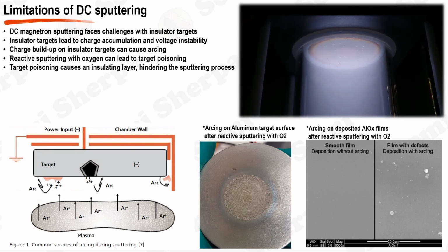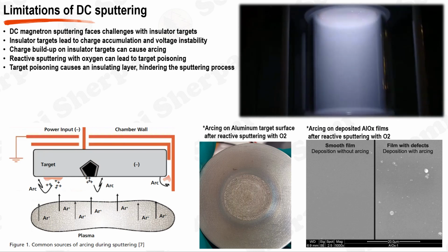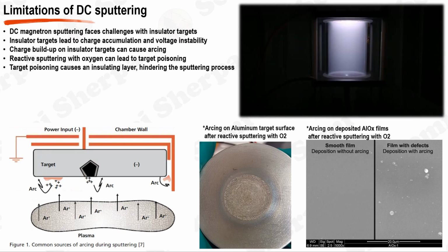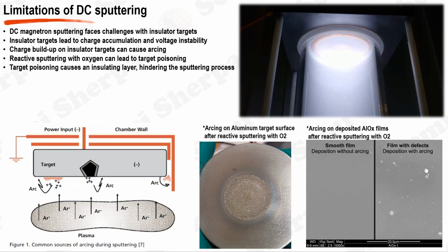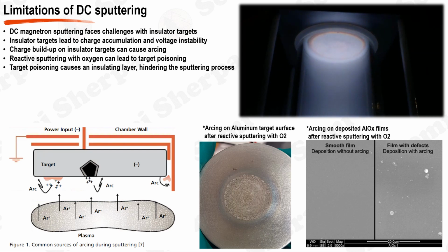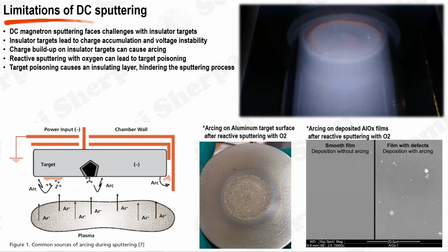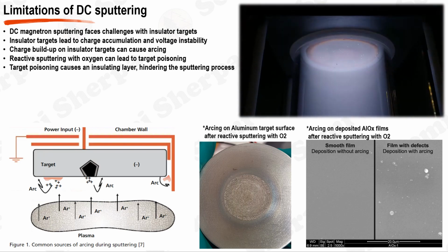The use of insulator materials as targets in DC magnetron sputtering poses a considerable challenge. The key to a stable DC plasma lies in the existence of a conductive target surface. DC plasma harnesses the voltage difference between the cathode and anode, inciting ionization reactions that in turn generate plasma. To uphold a current, the material in use needs to possess conductive properties. Essentially, conductive materials permit the movement of electric charge, thereby facilitating the direct current flow.